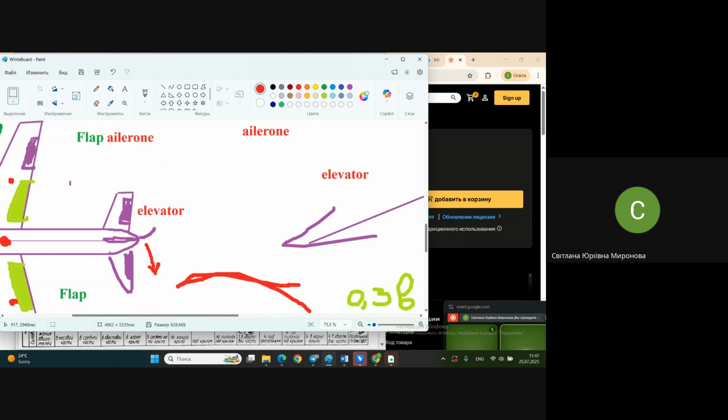They are placed on the rear surface of the wing. They are used as ailerons during the cruise flight and as flaps during takeoff and landing. So first they are flaps, next they are ailerons during all the flight, and next they become flaps again. What is the difference? How are they moved? Control motion on flaps results in moving them down to different angles, and control motion to ailerons results in moving one up and the other down. The decision is more complex technically.